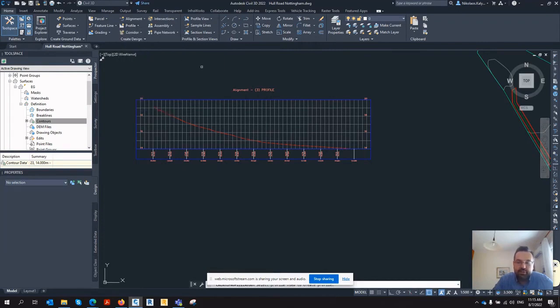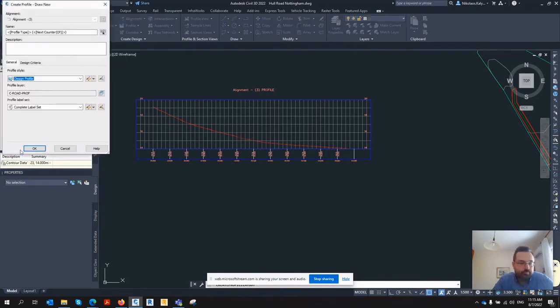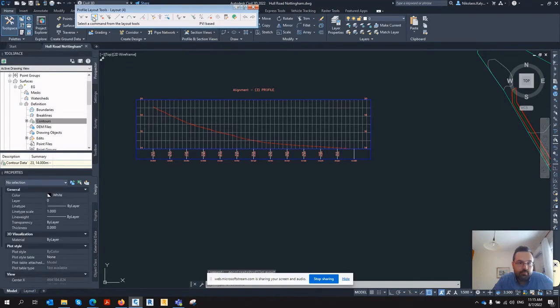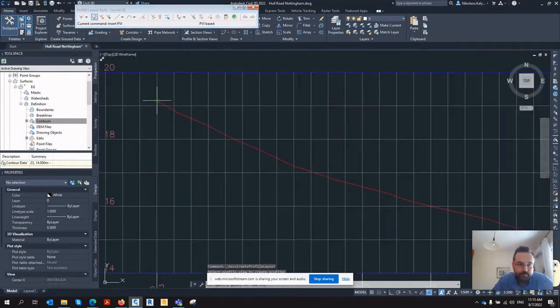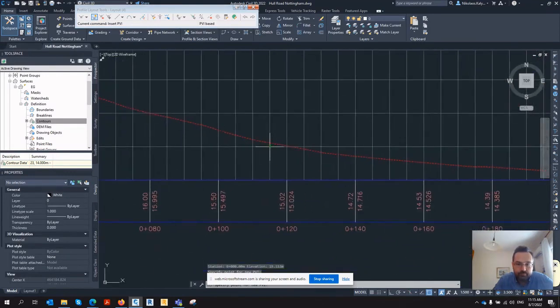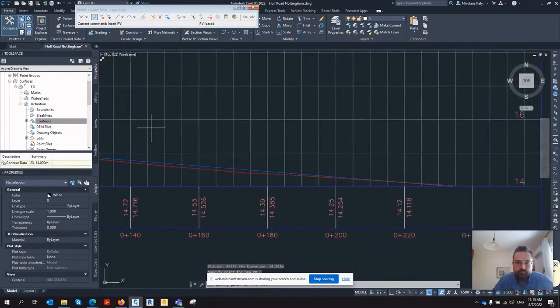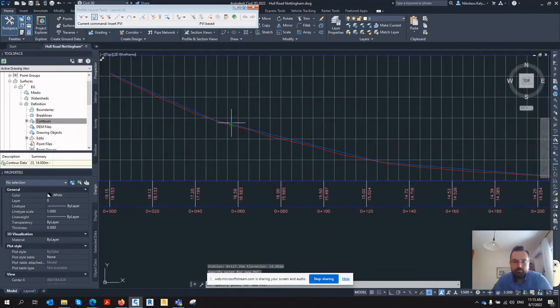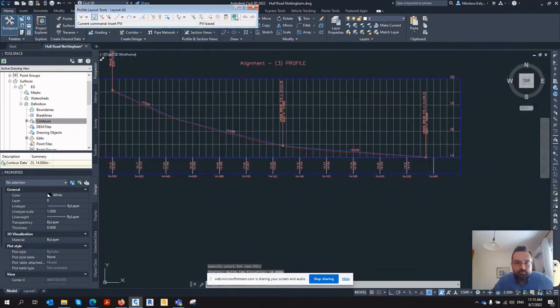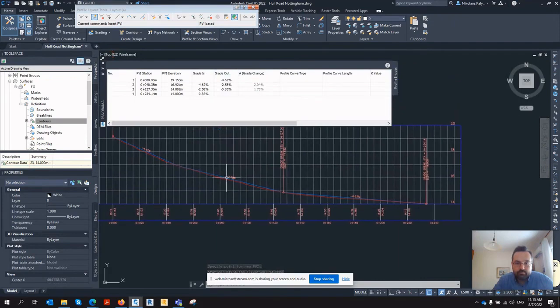To define the level of the new road, we choose Profile, Profile Creation Tool, and we get this menu. How we will design the profile of the new road is affected by a list of factors such as the maximum permissible slope or the drainage design.